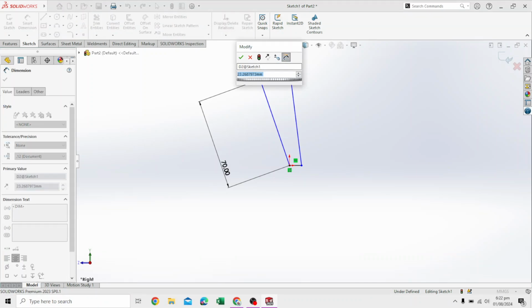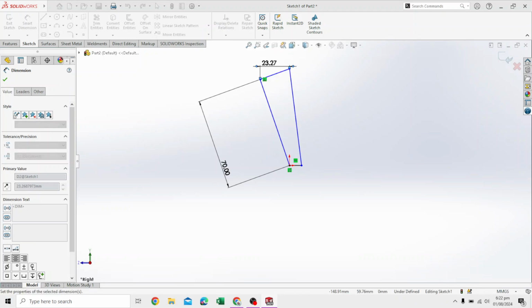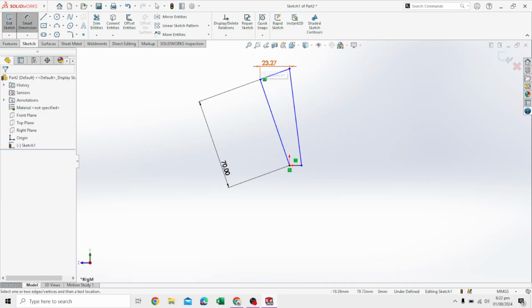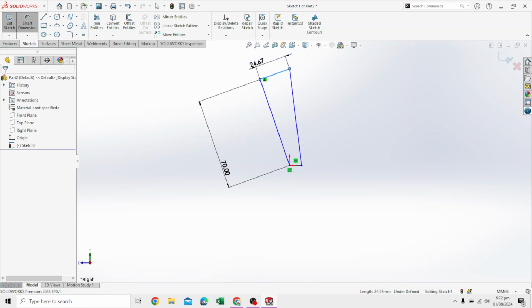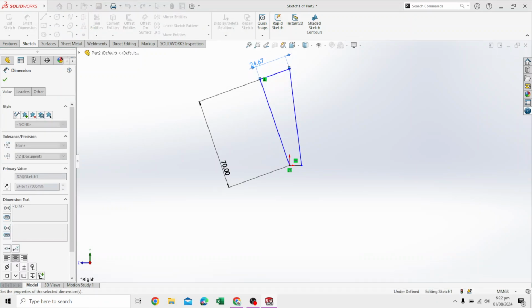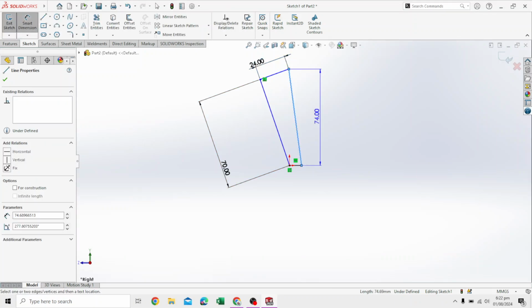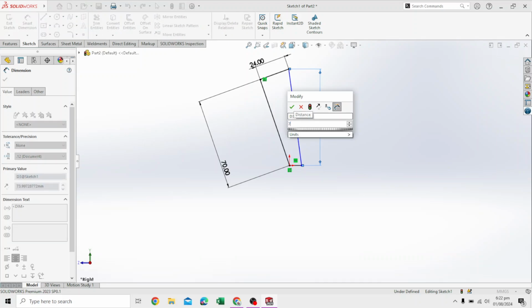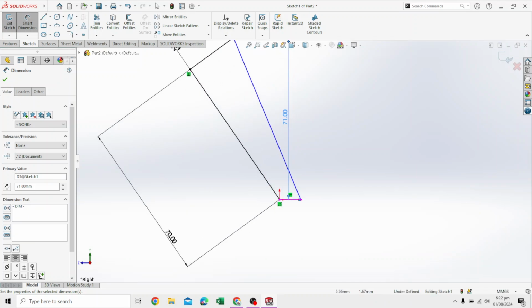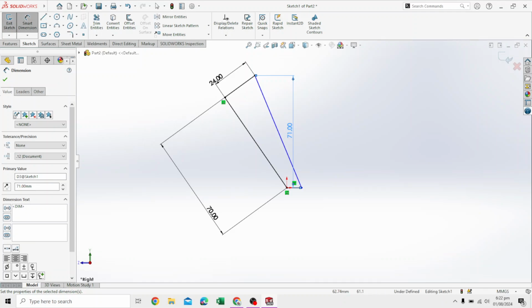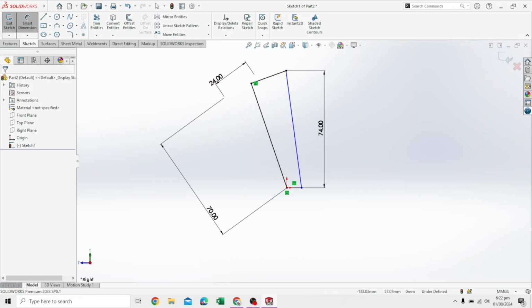no, not in this direction. Needs to be the measurement of, select this and delete, and dimension it again. It needs to be this. It needs to be in the same direction as the surface you're doing, otherwise it's the dimension of the shadow, not the actual value. 71. And then that's wrong as well. You just control Z that last command,